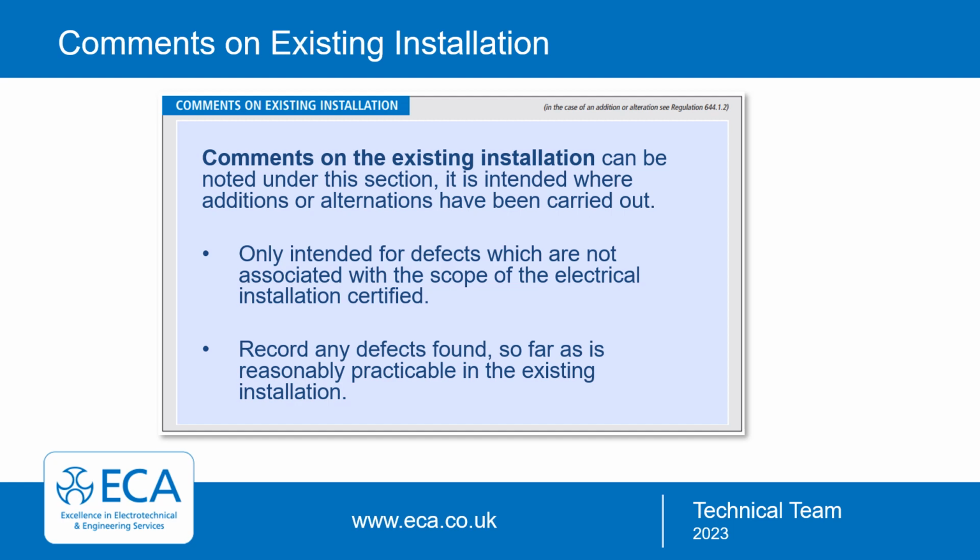It is also worth noting that in the case of an alteration or addition, Regulation 644.1.2 states that for an addition and/or alteration to an existing installation, any defect or omission that will affect the safety of the addition or alteration that is revealed during inspection and testing shall be corrected before the certificate is issued. So if you find problems with the circuits you're working on, you should correct those before you complete certification.